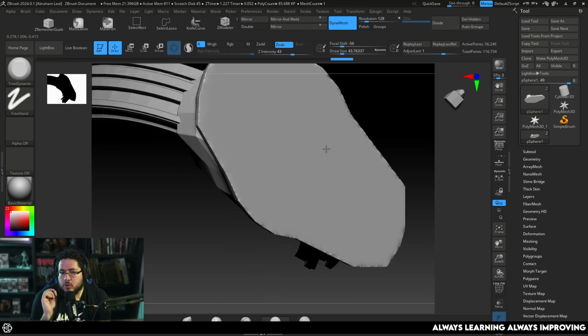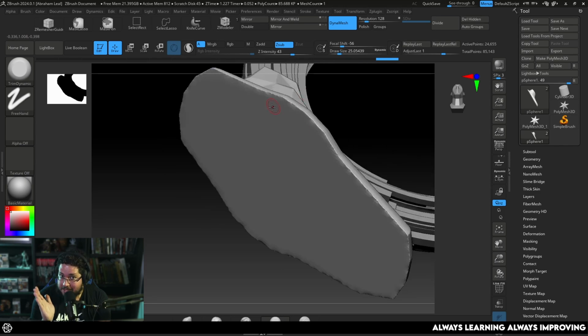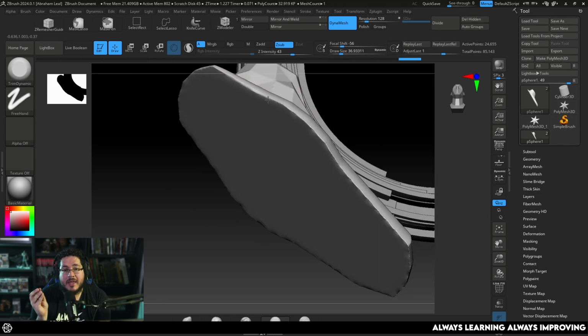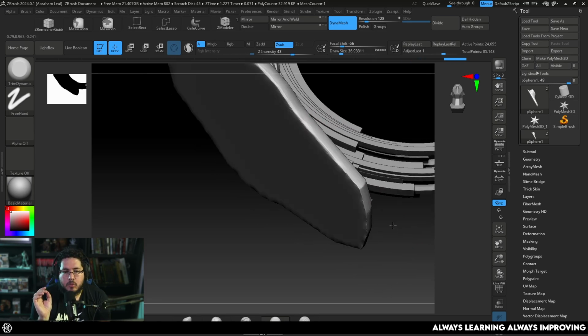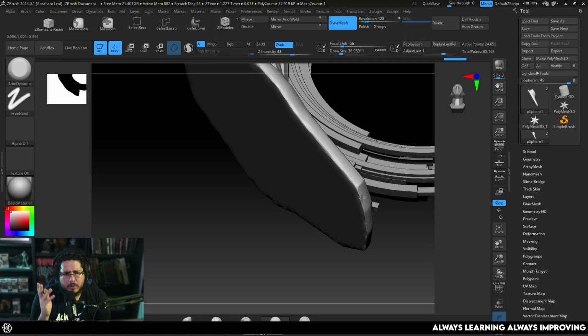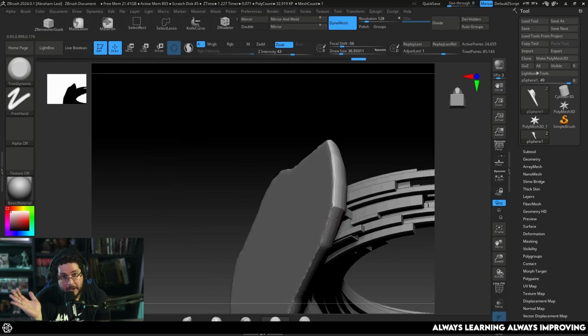The reason I'm doing this is because usually with these borders, especially if you're going to be 3D printing or doing bakes later on, having ugly n-gons and non-manifold geometry can really mess up the process. So I always recommend you guys clean these borders up, even if it takes a little while. I remember it took me here like 2 minutes or something. It's better to have clean edges than to struggle with other parts of the pipeline later on.